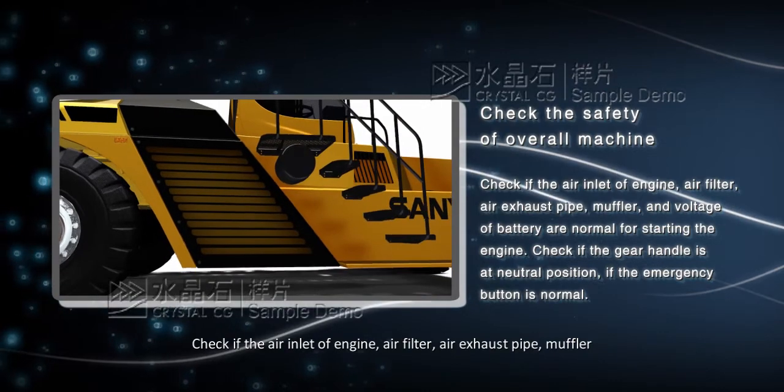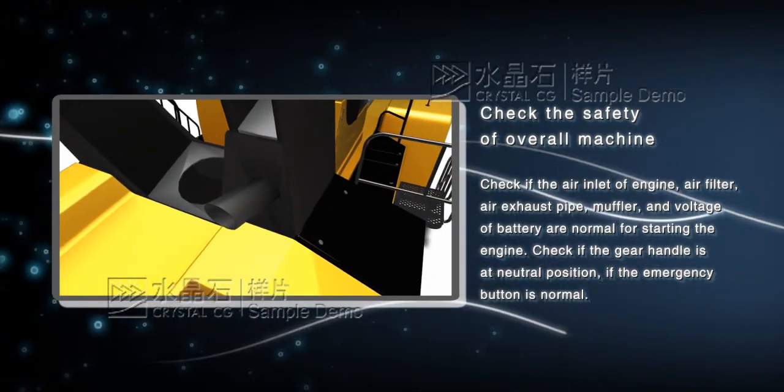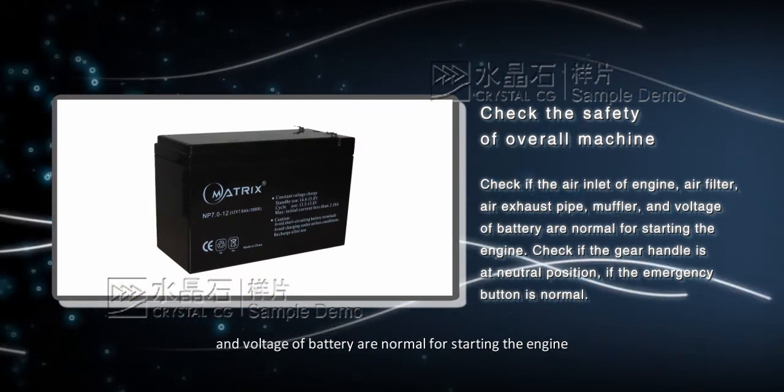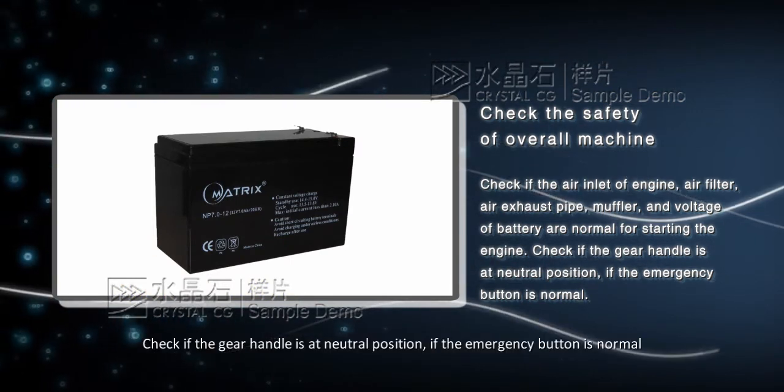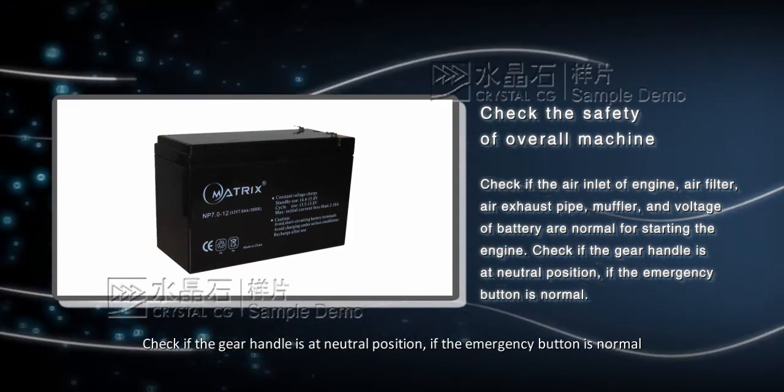Check if the air inlet of engine, air filter, air exhaust pipe, muffler, and the voltage of battery are normal for starting the engine. Check if the gear handle is at neutral position, if the emergency button is normal.